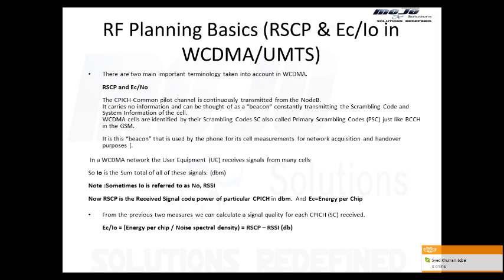Then what we do, we say, okay, for 40 watts power, there will be power for pilot and power for other traffic and other. In UMTS, as a rule of thumb, 10% is the minimum allocation for pilot power. For 40 watts, 10% will be 10 dB less. If 40 watts is 43 dBm, then it will be 33 dBm. I'm not sure 40 watts is 43 dBm, but let's assume 40 watts in logarithmic scale is 43 dBm.